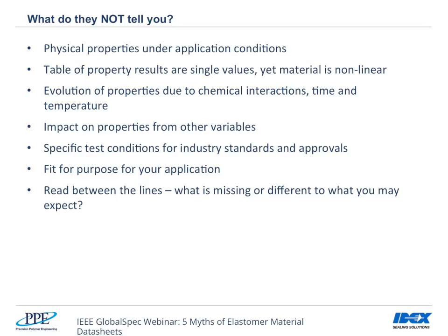So, what I would suggest, when using a datasheet, use it as a tool to help guide you and define whether that material is a candidate that may be suitable or not for your application. Once you've got a short list of materials, then the hard work really starts. Personally speaking, I would suggest reading between the lines. As you get used to using these data sheets, think about what information is missing or what's different to what you expect.